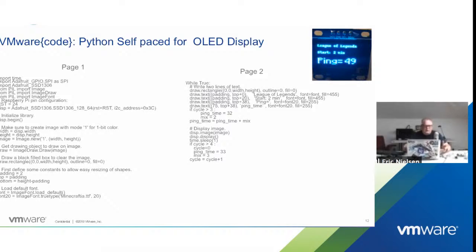Then I can draw things like a rectangle, but I'm going to blank the whole thing. These little OLED displays are interesting in that they remember what they did last. So the app could have died here. The app isn't running right now, I think. I don't think this thing's actually even booted. But because it has power, it's still going to show that code logo because it remembers the last thing it did. So I'm drawing a blank circle, fill 00, which says blank the screen.